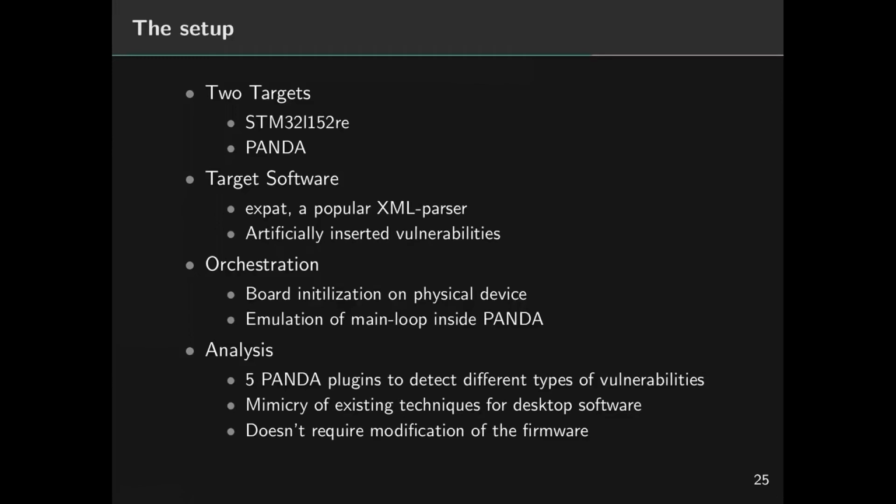For the analysis, we wrote 5 PANDA plugins which check and verify the state of the firmware during emulation by mimicking existing techniques used for analyzing desktop software. So for instance, we have something similar to a shadow stack implementation, and one plugin which tries to check the consistency of the heap by tracking malloced, freed, and realloced objects. The big advantage of this approach is that there's no need to modify the firmware.